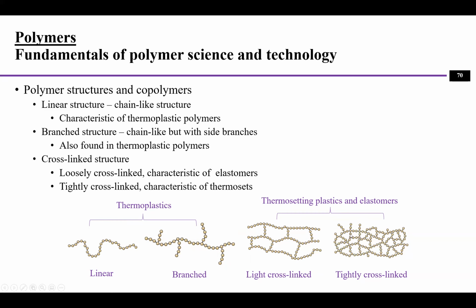So that's why you will see some polymers or plastics, we typically call them thermoset materials or elastomers. What happens when we melt them is that they will start to burn. So this means the materials are gone, and when you cool it back, it will not go back to its original shape or original structure. So that's the difference between the thermoplastics and also thermoset plastics and elastomers. And that's probably why you notice that some plastics will burn, some of the plastics will just melt.